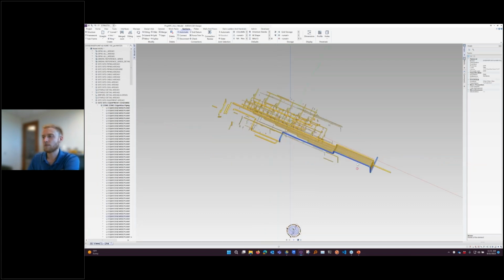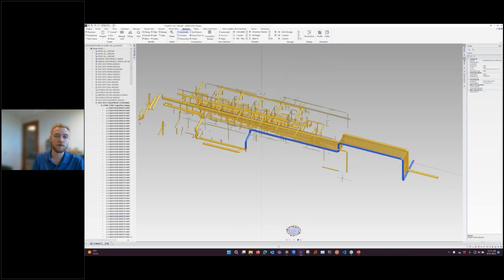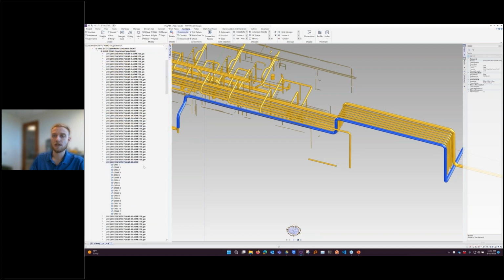Now, if I look at this model, this is our system. The key that we did for the equipment modeling is we broke up the equipment based on layers and based on the pipe runs that are defined inside of EdgeWise. In this case, this single pipe run is made up of this equipment. The naming convention follows whatever we define for that prefix, and then whatever data we have in there. So in this case, we call it ASB 150 PSI. If I add that layer name, it will be in there as well.